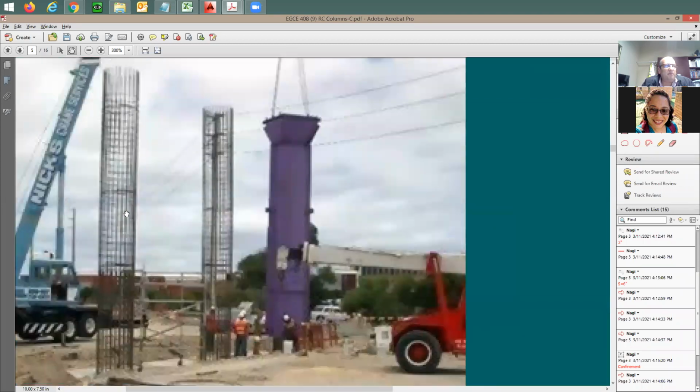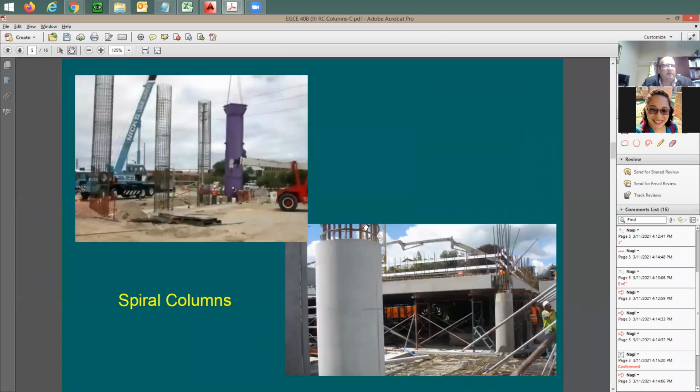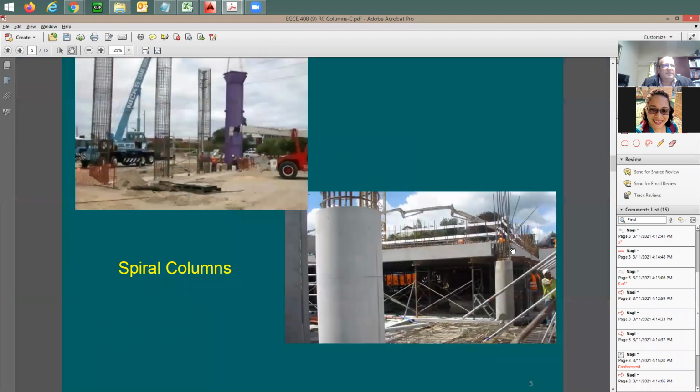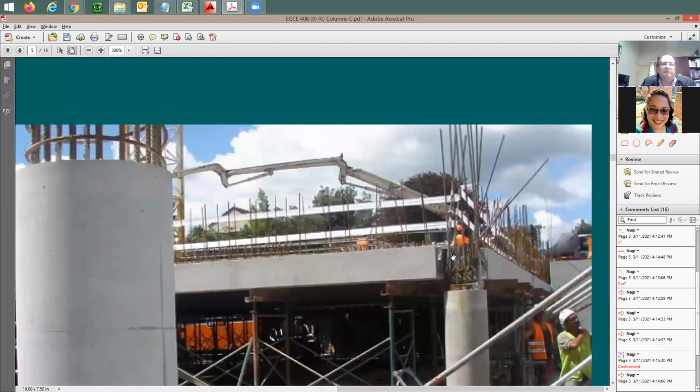This is the spiral, just going throughout the whole thing. Same thing here. And again, you also have the dowels extending above the concrete deck or concrete slab, and then you bring more rebars and splice them here. We call this the splice, because you put this rebar next to that bar. We call this lap splice because you're overlapping the two bars like this. This length, from here to here, is what we call the lap splice of the rebar.